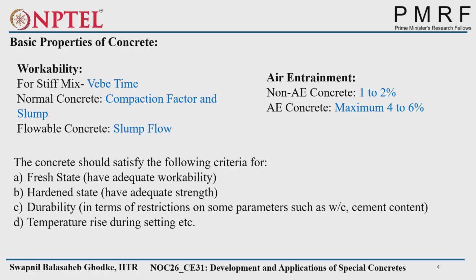So basically, fresh concrete should have adequate workability to be workable in the proper conditions. Hardened concrete should have adequate strength. For durability, there are certain Indian standard provisions: how much water content we have to consider, and how much higher amount of cement we can consider. Beyond that we should not go. Those conditions are in the Indian standard codes for the durability aspects. And temperature rise during setting. Where will we find temperature rise to be one of the major problems? Which type of concreting?